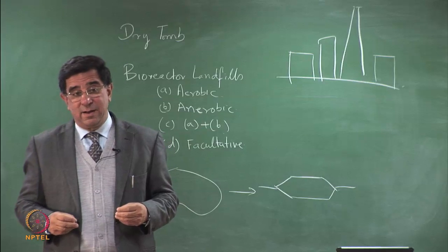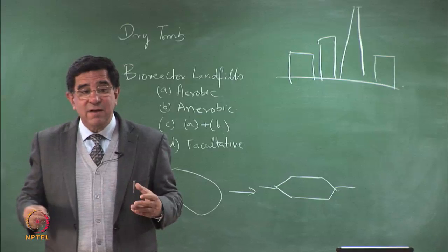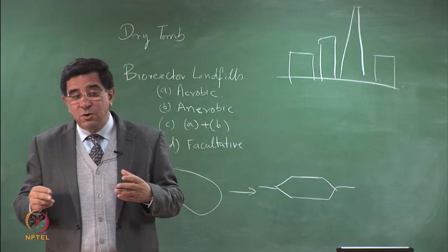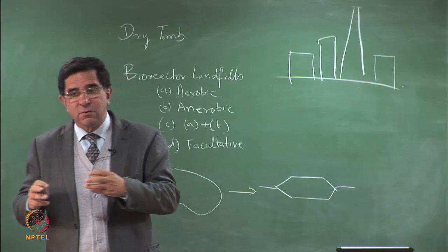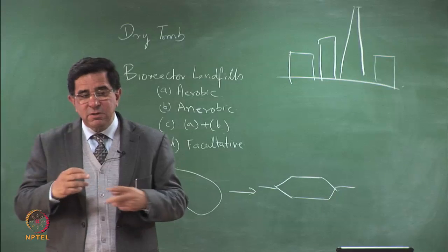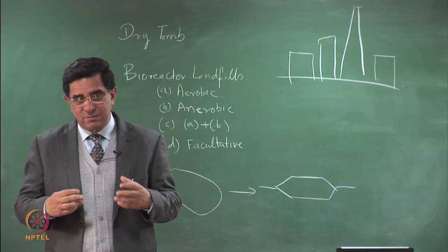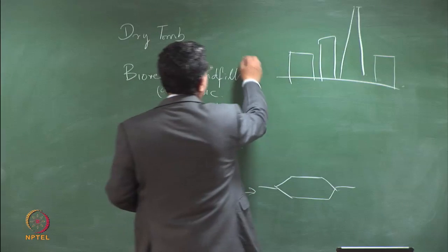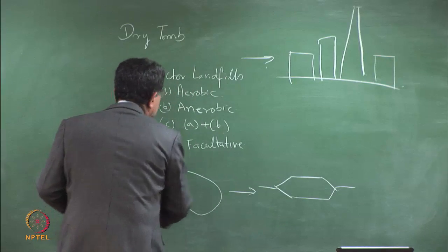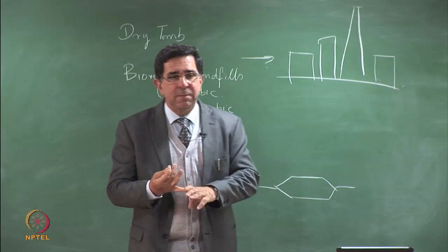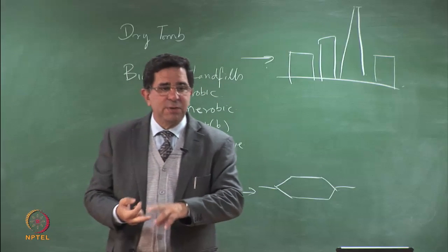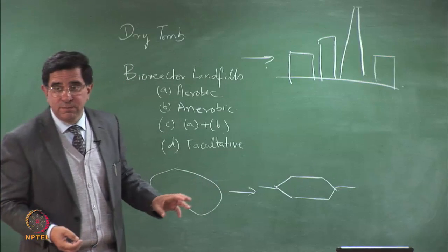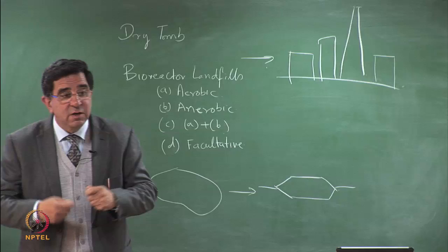Well, if you make a bioreactor landfill, in how much time does it stabilize? Yeah, so it goes from tens of years to years. It doesn't go from tens of years to weeks. So I'm just giving you 2-3 alternative comparisons. One, in a closed container facility like this, the waste coming in, we have more control. We have control over temperature, we have control over humidity, we have control over pH, we have control over oxygen. In a facility like this, we can attempt to do control. But it's not that closely possible.